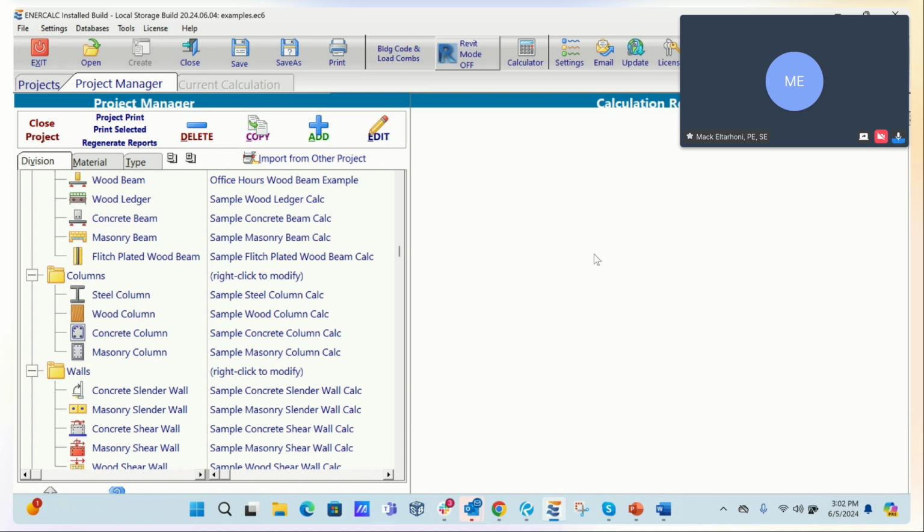Definitely most of the time, I'm talking from my experience working as an engineer, I normally take the envelope reaction. I never try to carry the specific type, if it's dead load or live load. This is too much work. So I'll just carry the envelope reaction and apply it as a dead load. That, of course, creates extra, so that's a little too conservative, and that carries down a little bit.